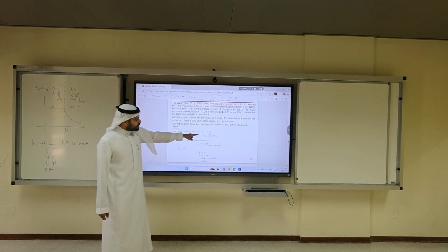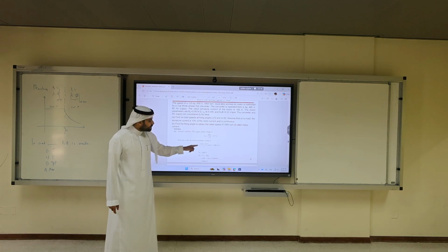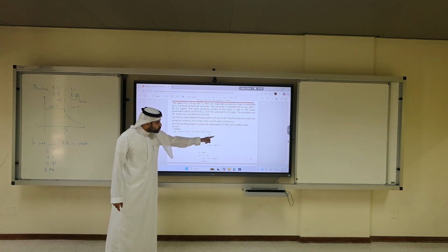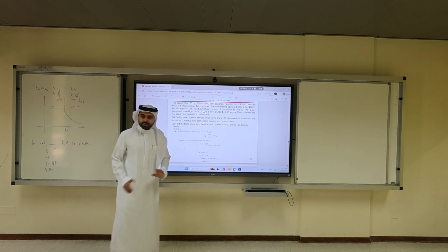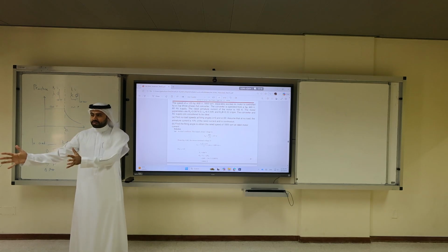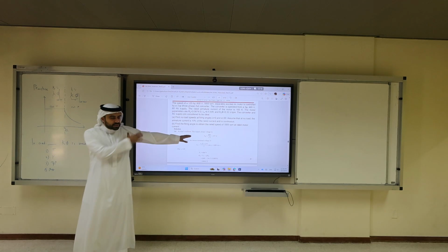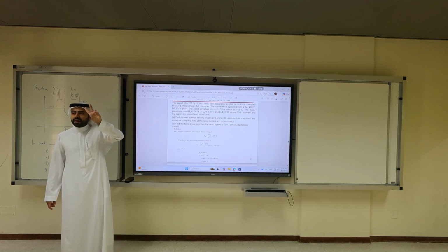So here, the first step is to divide by square root of 3. Then to get VT, you plug in 277, not 480. Then you get VT equal to 648 cosine alpha. That's the effective DC from the power converter. This is the equation if it's three-phase. These two equations are important, even in real life, they are used.